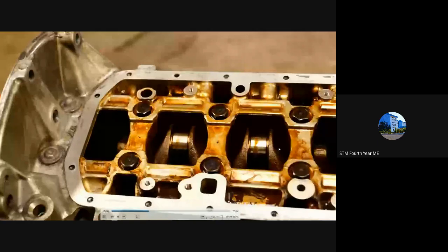Okay, the crank is exposed here. Now we have to remove the crankshaft, so these bolts are very important. So these bolts are present in the crankshaft bearing journal circle. So these are points where the main journal is. So journals hold the crankshaft in place. Journals are points that hold the crankshaft in place inside the engine block, so that the crankshaft will not move sideways or in any other irregular ways. But we only need the rotational motion of the crankshaft.